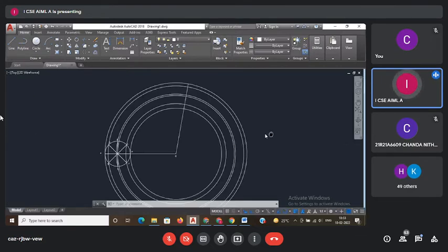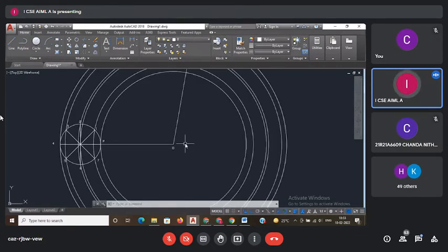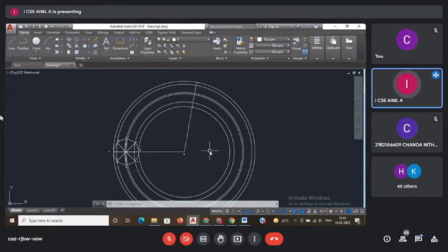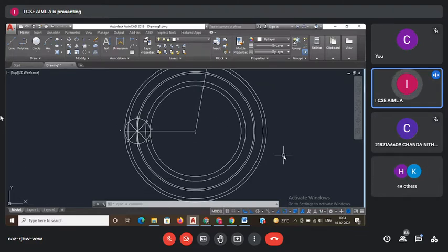But now here you don't know the end point. You have circles. That's why you have to find out the theta. How to find out the theta? Capital R by small r into 360 degrees. Okay. Then after this, remove unwanted lines. Unwanted arcs or circles and all.